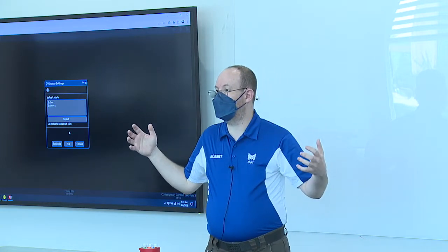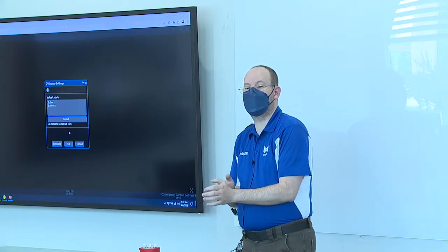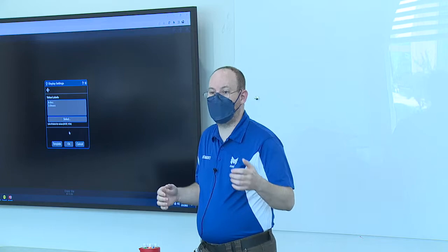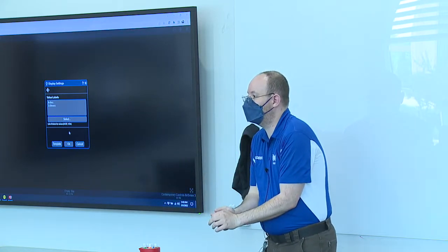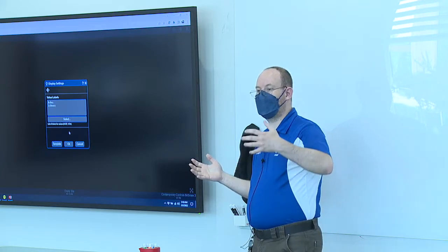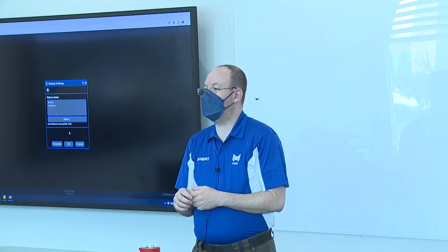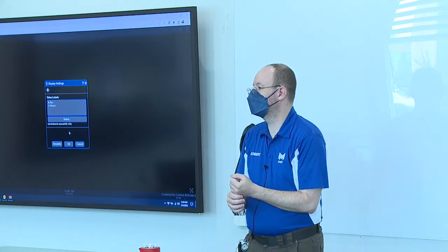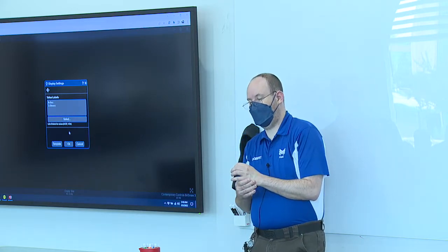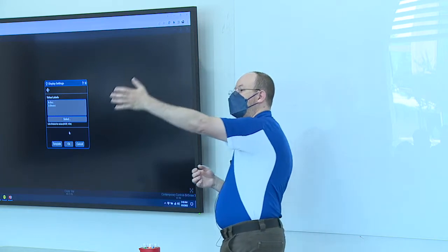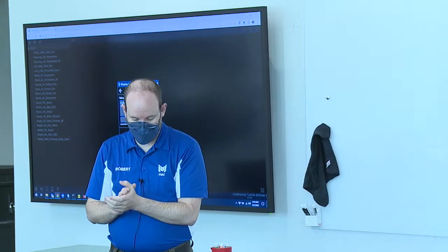Who in here has dealt with this? I know this isn't going to apply to Ramiro down in Palm Springs or Palm Desert. It's probably not going to apply to our friends from Texas either. But for those of us in the more northerly climates, what happens if you lose power to an outside air damper? It depends. What does it depend on, Bob? Depends on where it stopped. Is it open? Is there a crowbar in there?